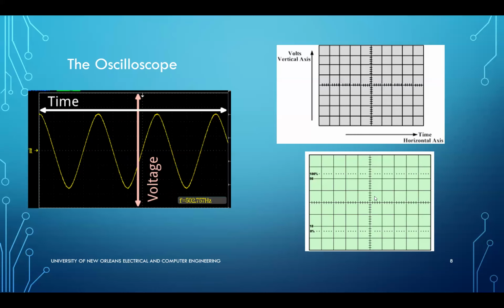I've said that this one has a little more detail because inside the squares here, you see little ticks, right? And that gives you a little more detail on what you can see on the scope. So for example, if you go back to the idea that each vertical position is set up to 1 volt, then each of those ticks will be 1/5 of a volt.